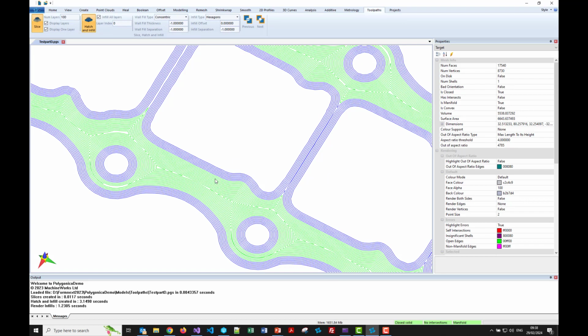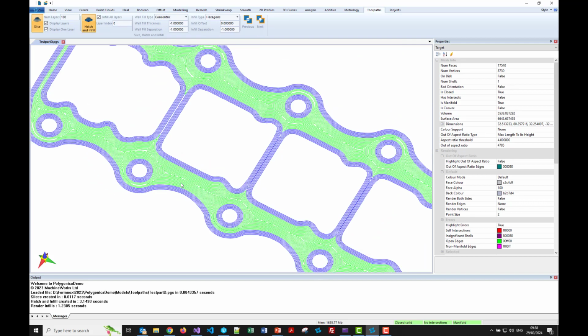Here we've got two concentric patterns. That's because in 3D printing applications, it's nice to have an external boundary around the infill, and you need an external boundary in the walls, but also at the top and bottom. So this example code that we've written creates both. In this case, I've given the top and bottom the color green, and the stuff around the sides the color blue. They're both the same thickness. The green is that thickness vertically, and the wall is that thickness horizontally.